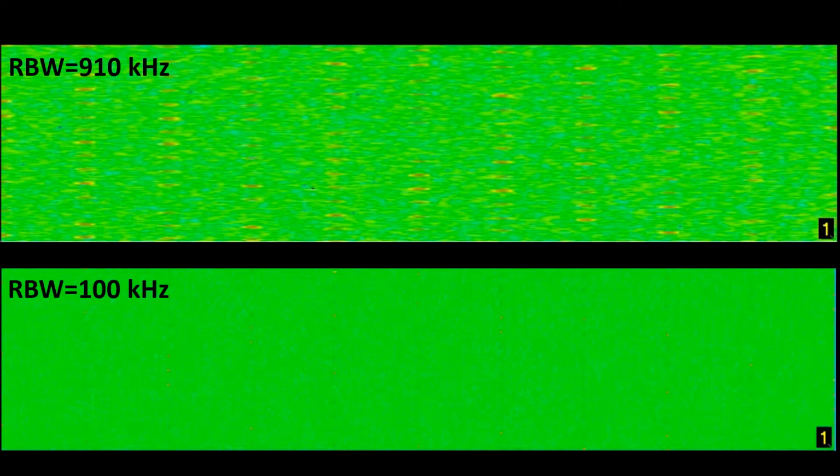If we reduce the resolution bandwidth, we can improve the estimation of the frequencies and even reduce the noise floor. But then the measurement becomes slower and we start to miss details of the time evolution of the spectrum. If we try to tune the configuration parameters, we might improve the spectrum visualization a bit, but we really need something different for this kind of spectra.